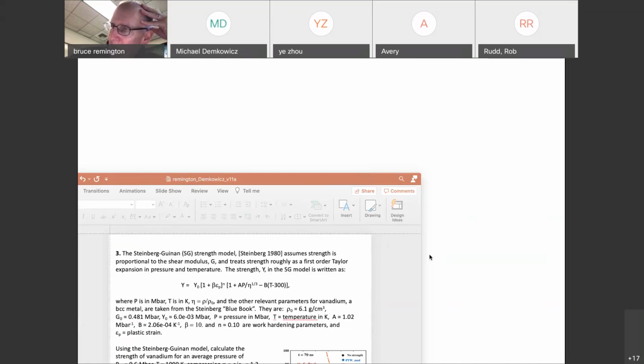And there's a very nice article in Nature by Chris Wehrenberg. I think the date was like 2013 or 2015. We went to LCLS to do it the first time because we were worried we wouldn't be able to see that dynamically. We'd been seeing that in recovery with Marc Meyers for quite some time. But to look for that dynamically was hard. We went and did the experiment at LCLS and there's a very nice Nature article that describes that with Chris Wehrenberg as the first author. And then once we saw what to look for, clearly, we went to Omega and did it there as well. So you can study slip and twinning dynamically.